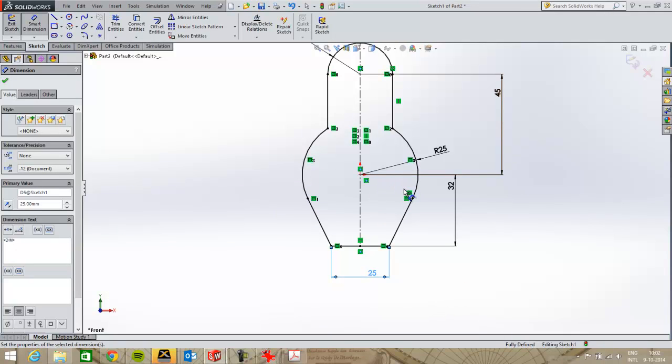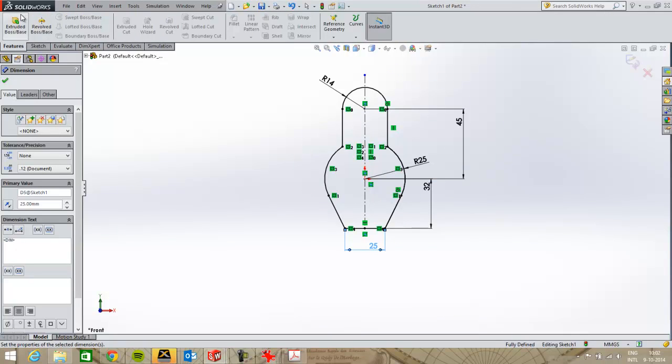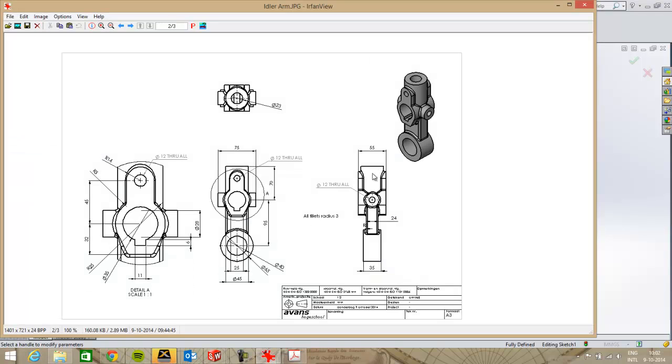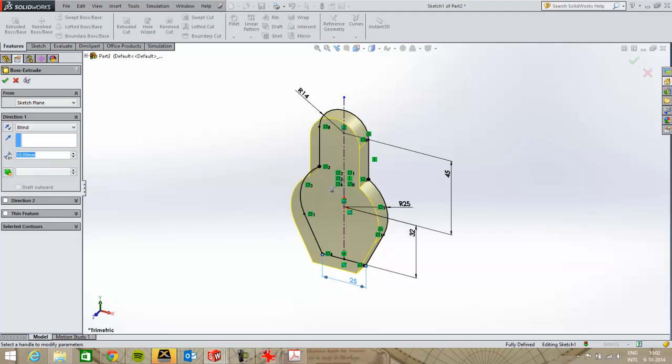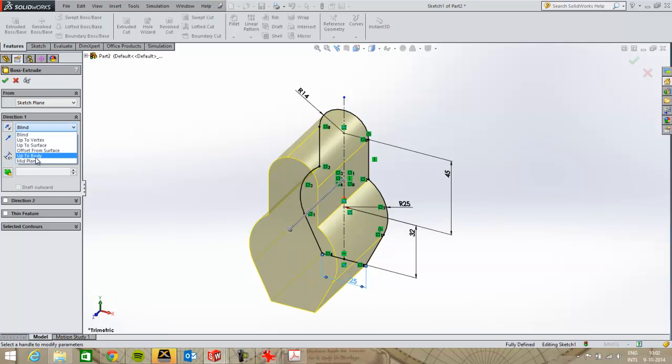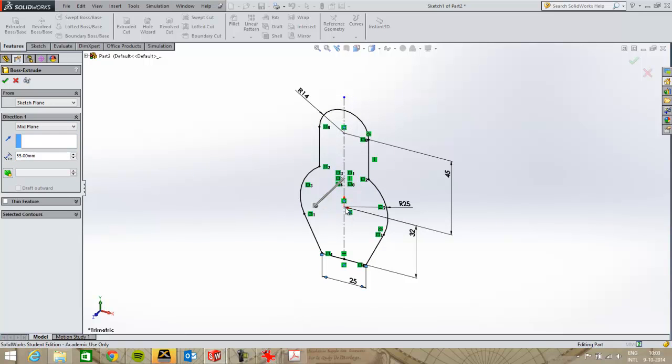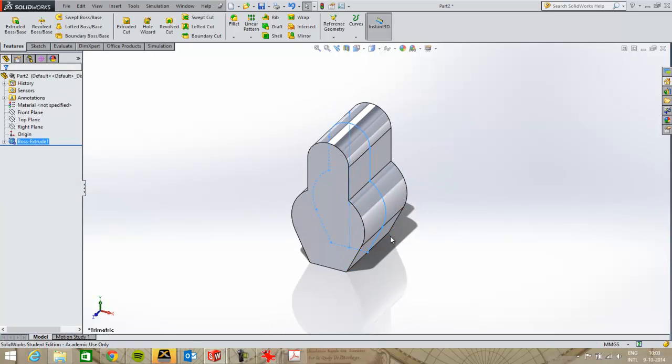you see it over here, and everything has become black. And now it's easy to model in a symmetric way, and the width of the parts are on this drawing view. So this one should be 55 over here. So I'll enter 55, and then in a symmetric way. That's very important. So I use midplane. If you do that, then the center of this part will always be in the middle, and that makes it easy.